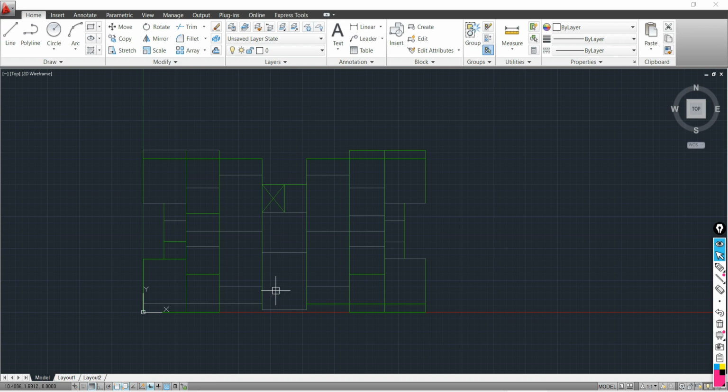First you have to export, then you have to set the origin at 0,0. Sorry, you have to open a new CAD file, then copy the center line plan from the base file and put it in the new file, with your positioning as 0,0. Got it? And you have to save this file in the DWG format, right? Correct. DXF format. Yes, in DXF format, not in DWG.